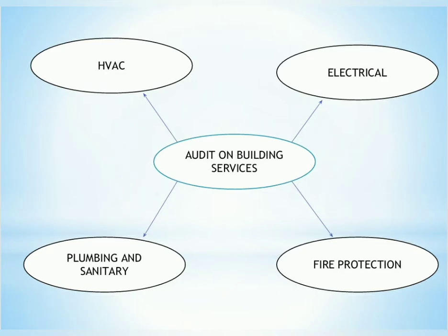The identified sanitary and plumbing system defects pertain to: first, general plumbing issues, for example water supply general defects and leakage joints in inaccessible areas. Second is underground and overhead storage tanks. Third is the water supply system, for example corrosion and scaling of pipe valves, damaged pipes, water hammer, and excessive vibration. Fourth is general pumps and sewage pumps. Fifth, sanitary fixtures and fittings. Sixth is sanitary piping. Seventh is sewage ejectors, and last one is sewer and manhole.